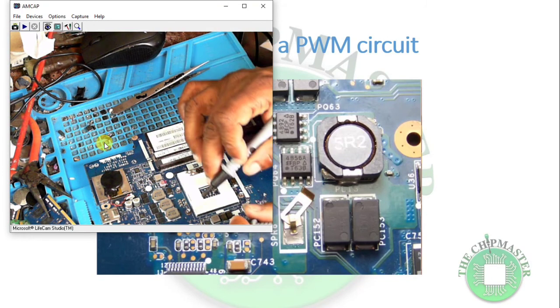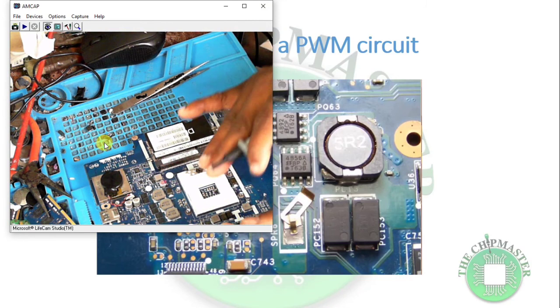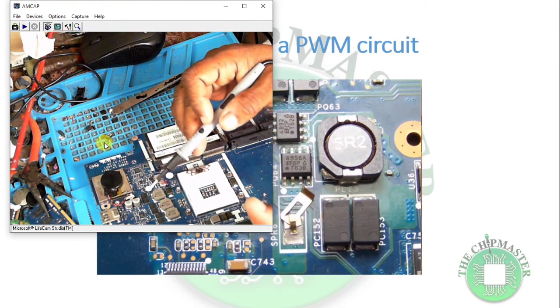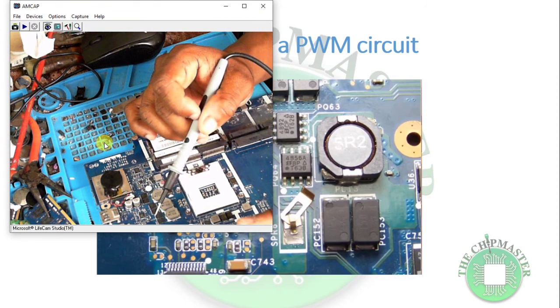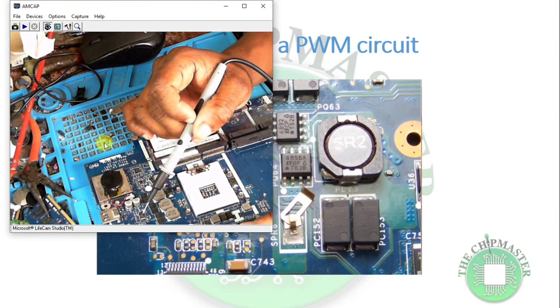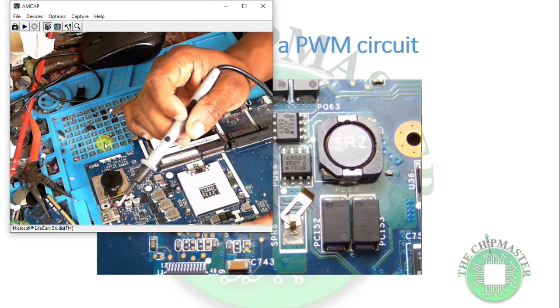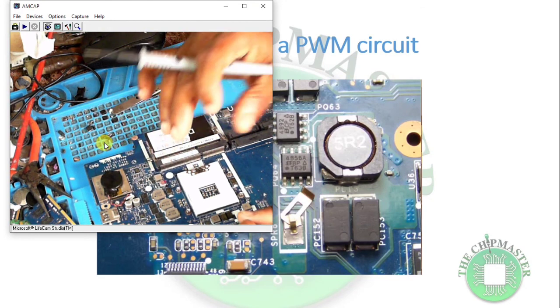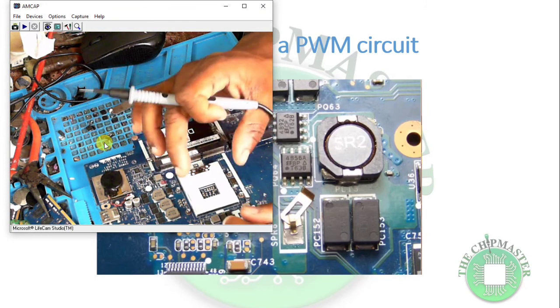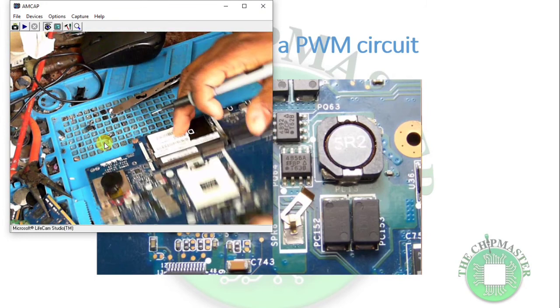If there is any fault, if the current is too high and the temperature is too high, then there's another NTC resistor. That resistor is going to basically tell the CPU, through the therm chip pin, to shut down the computer because it's in over temperature, it's too high. Alright, so